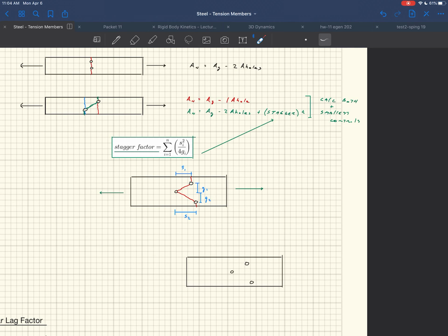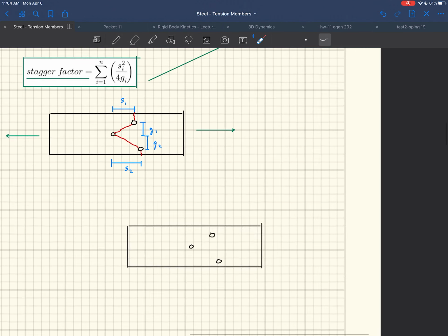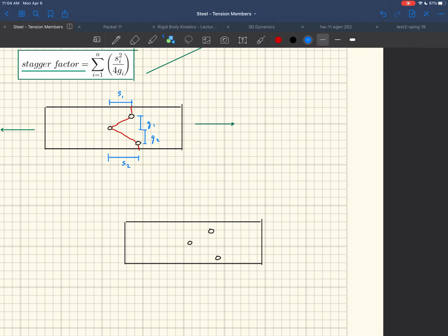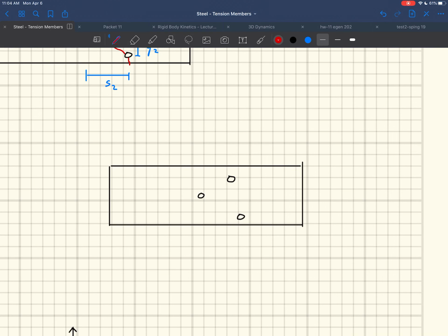Okay. The other thing, right, just to come back to this. So those are what your staggers are, right? For this particular example with 3 holes, you'd have to look at, right, is it going to rip, just going to get used to playing with this thing. Is it going to rip through here? Is it going to rip over here, come back here, and then down? Or could it possibly go here and then over and then down, right?